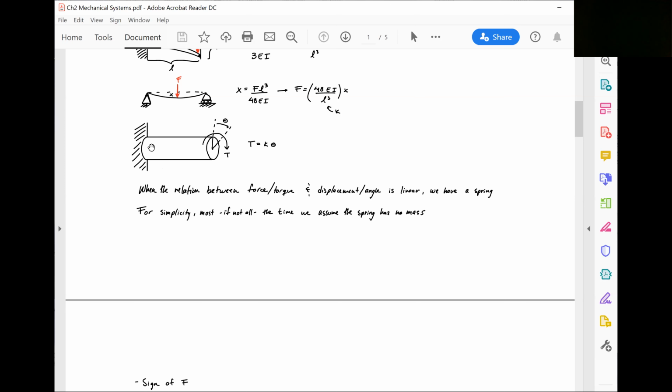When it rotates, this doesn't act like a solid object. Even the hardest steel, when it is long enough and the load is hard enough, has some difference between this angle and that angle. It has some springiness in it. And you have to model for that, because when you brake, it changes your motor.